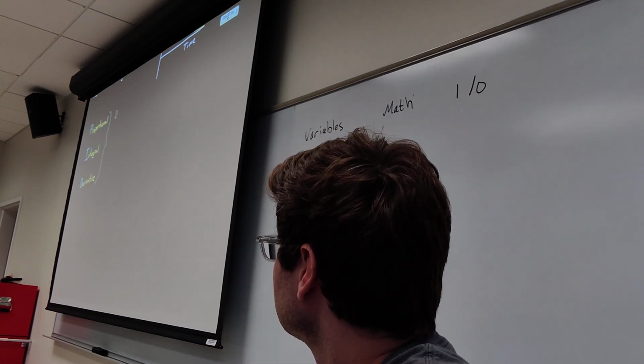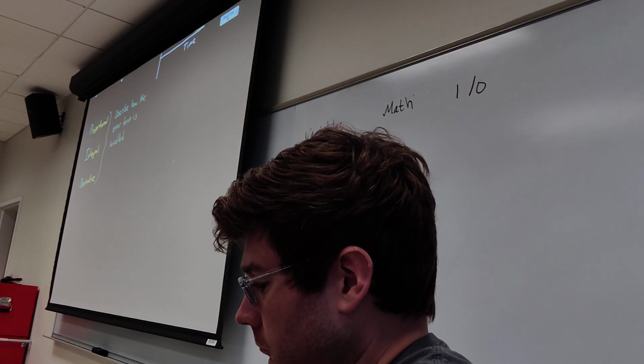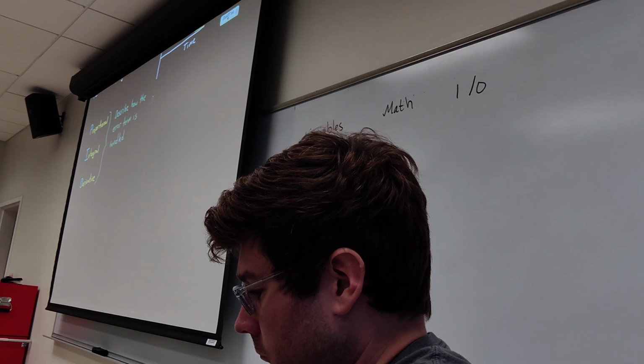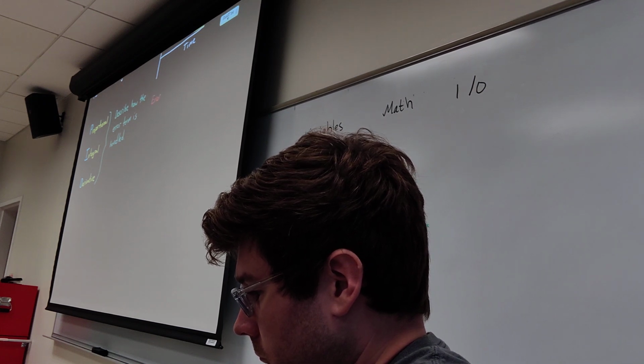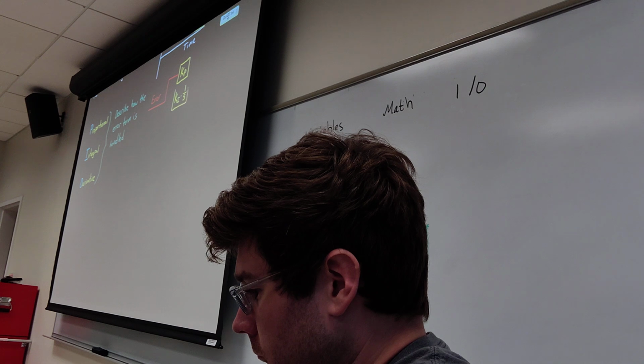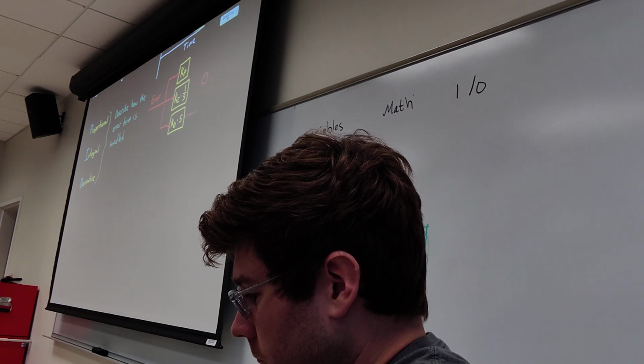And each of these terms describe how the error term is treated prior to being summed and sent into the plant. In one of its block diagram forms, a PID controller can be written like this. In the proportional path, the error term is multiplied by a constant Kp. In the integral path, the error is multiplied by Ki and then integrated. And in the derivative path, it's multiplied by Kd and then differentiated. The three paths are then summed together to produce the controller output.